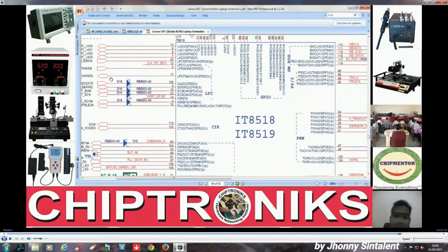You got my point? What is the process? As I said, there are two kinds of controller. One is inside the desktop keyboard, one is inside the IO controller. The keyboard encoder present inside the desktop keyboard is 8048. The keyboard controller present inside the IO controller is 8042. When you press a key, current flows.